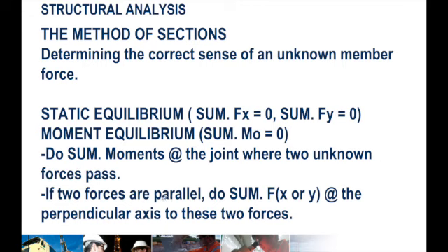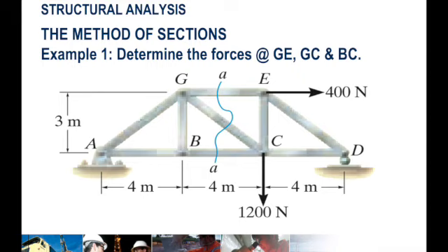So if two forces are parallel, do summation forces X or Y at the perpendicular axis to these forces. So those are just some tips in order to do our calculation faster and simpler. Okay, so now let's do an example.